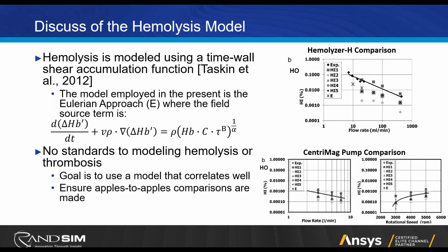And so that's where we would use these models, not to say I know my design is going to have exactly this much hemolysis, but as a way to say that between these three prototype designs, prototype number 2 is going to have the least amount of hemolysis for the best performance out of all of them. So that one has the highest likelihood of passing clinical trial tests, even though maybe prototype 3 has better actual performance, with a better pressure differential given the flow rate or a lower torque on your impeller.